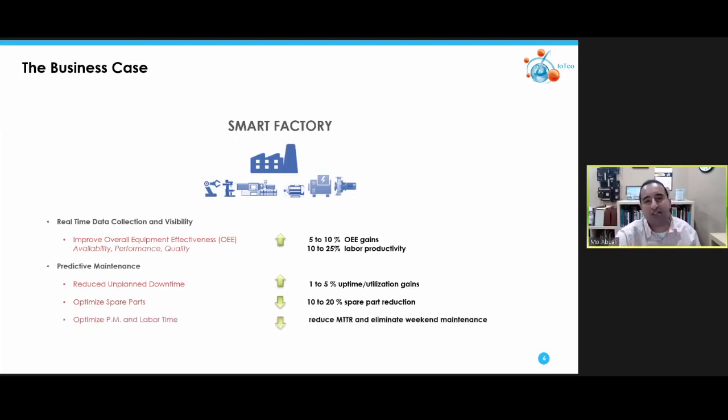Many manufacturers are running systems like SAP PM and IBM Maximo and other systems, right? And those systems are usually detached from the operation. They are more manually driven systems. So by taking predictive insights and tying them with your maintenance system, you provide a heads up not only to order a spare part, but to optimize your maintenance activity, to schedule a maintenance person to fix the machine before it fails, to reduce your overall mean time to repair, and to improve your mean time between failure, right? MTBF and MTTR are two key maintenance metrics that you want to impact positively by using industrial AI.